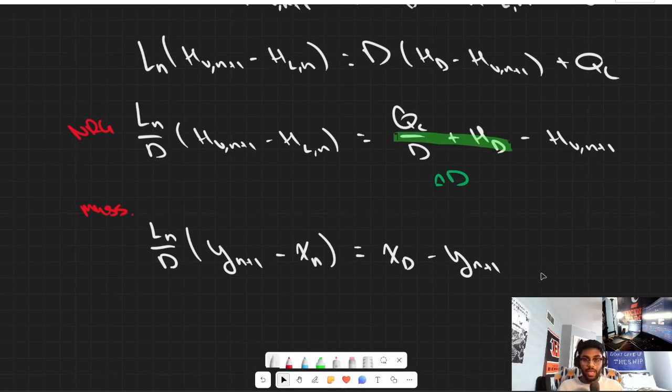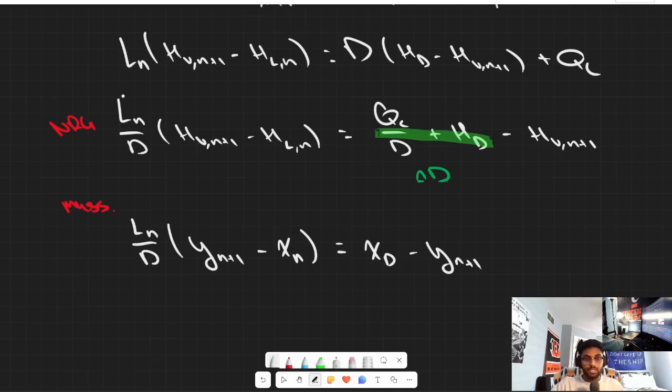So now we have these two analogous functions that are representative of our energy balance and our mass balance. And using this relationship, we can go ahead and start plotting out the straight lines for our stripping, or not our stripping, but our rectifying section, and prove mathematically why this Ponchon-Savarit diagram is designed in a way to allow us to find that vapor mole fraction based on the enthalpies.